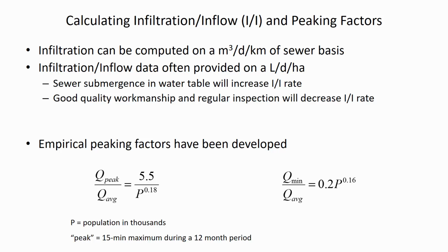Okay. All right, so you guys are hitting on an important factor. So part of it is related to, in a small town, maybe everyone works at the same employer. Everybody's working at the local mill or the local factory. And so in a large city, there's, the city that never sleeps. People are going to be showering and washing dishes and flushing toilets at all hours of the night. So it's partly related to human behavior. And it's also partly due to the geographic diversity. So that if you have the water all going towards some central sewer plant in a big city, it takes a long time to travel there. And that dissipates the peaks.